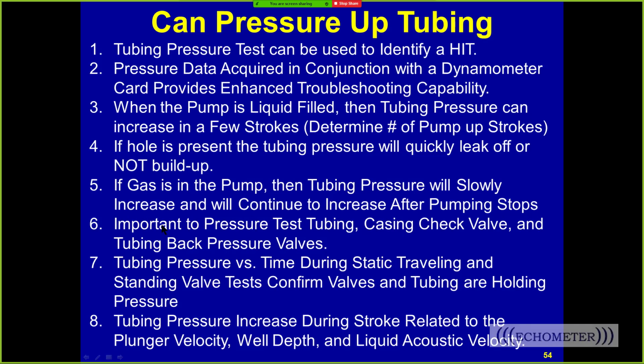When you do a pressure test, you should have your valves arranged so you can pressure test the tubing and then open the valve and pressure test your check valve and pressure test your back pressure valve and make sure they're all holding like they should be. And so that's an important test to do. You can do the pressure test in your valve test and confirm that they're holding, or after you do a valve test, again, do a pressure test and confirm that they're holding pressure.